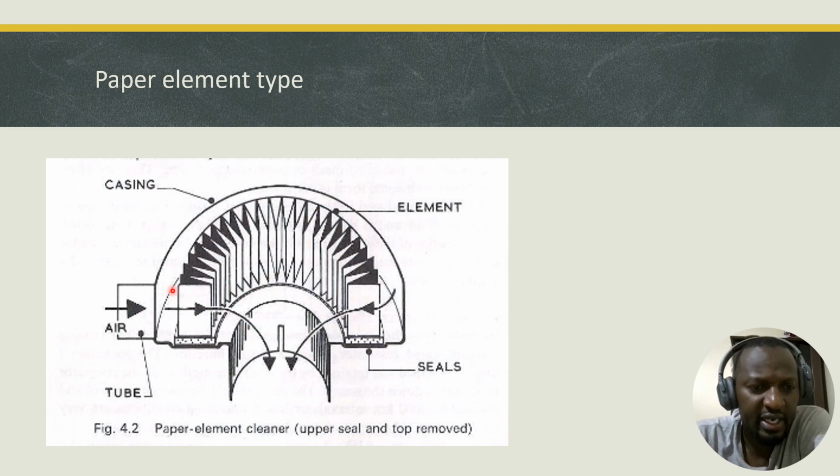comes to the engine. Now, dirty air is forced to pass through the air cleaner from the outside or the peripheries, and dirt particles are cleaned out, and then air passes through the center column and into the main air tube and is charged into the engine.